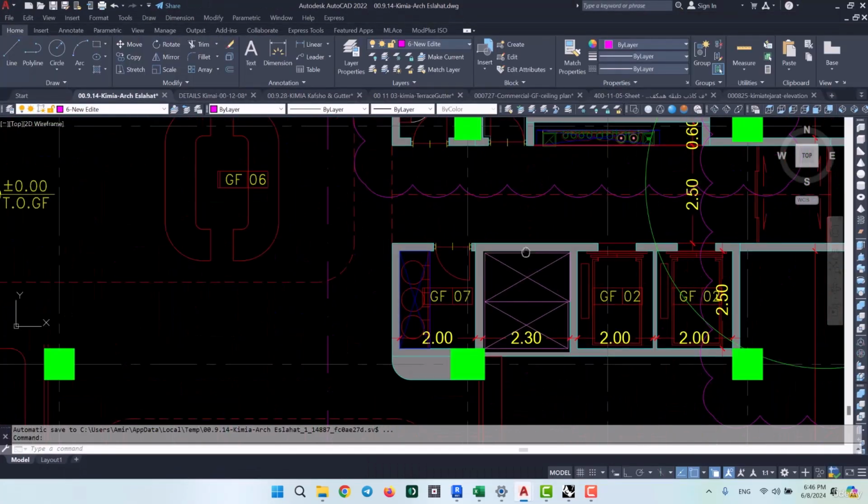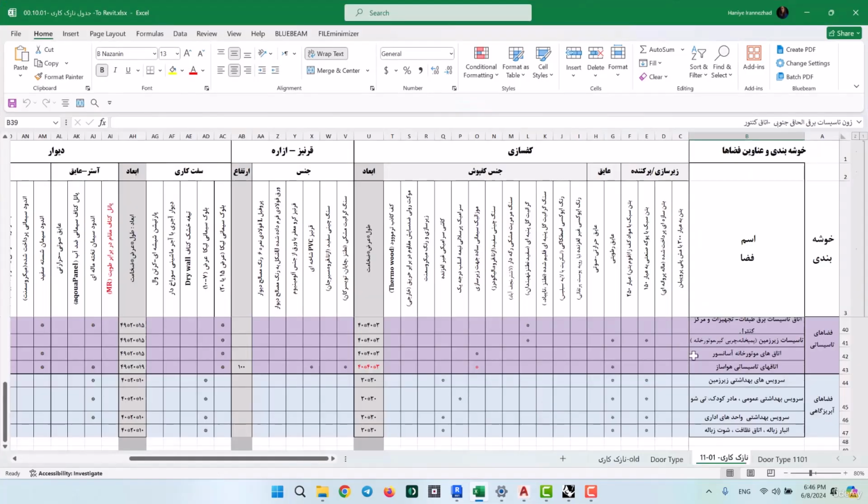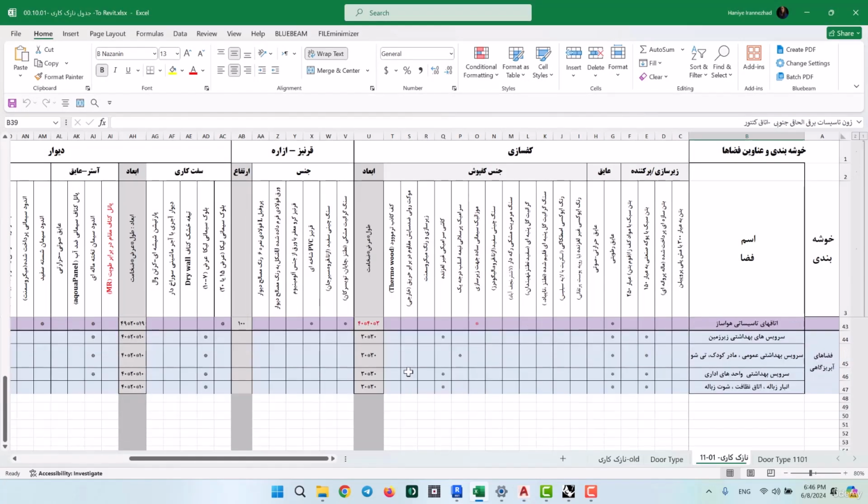And you see, for example, that area was for the garbage chute. Now, based on the finish table, what was the material that we needed for that part? It was supposed to be non-slippery ceramic with dimensions 30 by 30. Now, here's the thing about this part. We did say that our FFL was supposed to be 10 centimeters from the SSL or the TOS level. So basically that just means that our floorings need to be 10 centimeters thick.